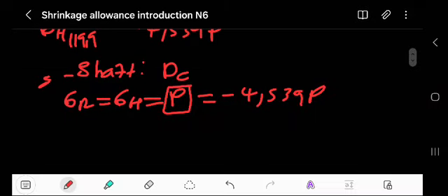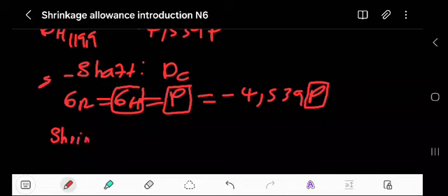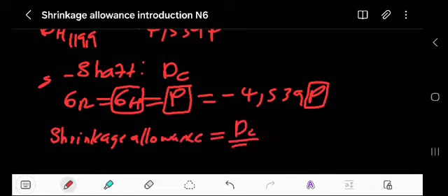Okay, since you know that, now we have our hoop stress. The aim is to calculate P. How can we make P the subject? We know the shrinkage allowance is given. I can write this in name so that you can see it: shrinkage allowance is equal to common diameter over modulus of elasticity times the hoop stress of the outer minus the hoop stress of the inner.